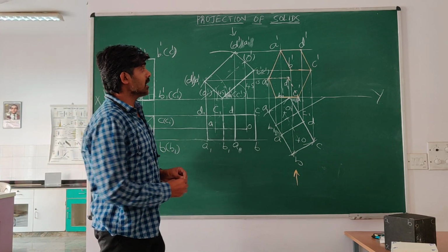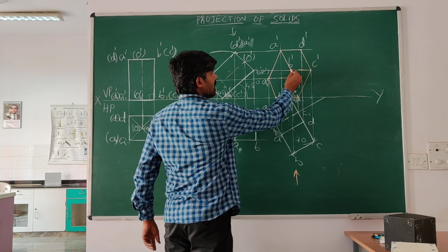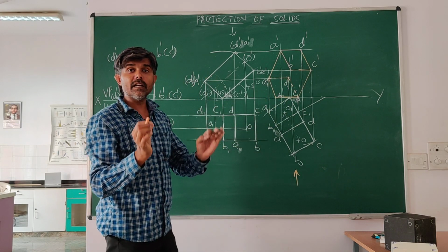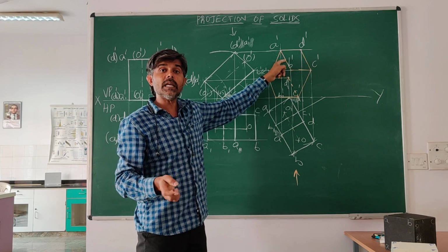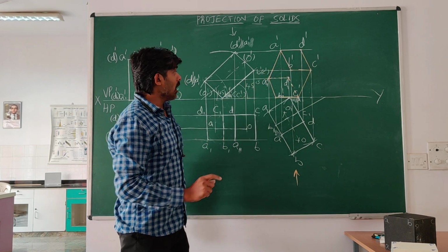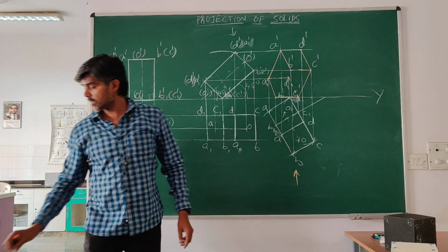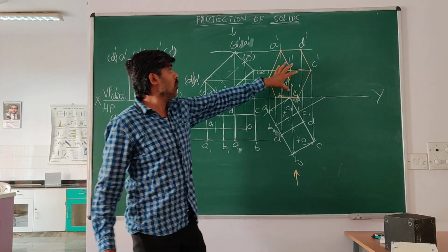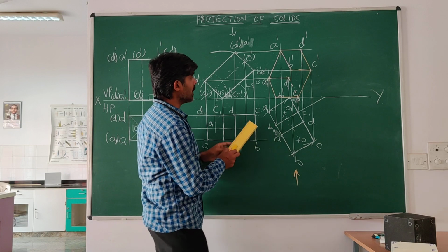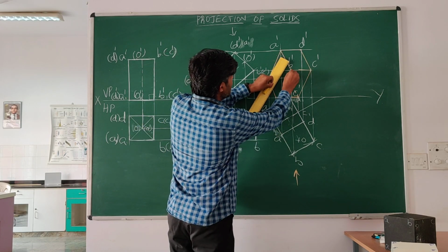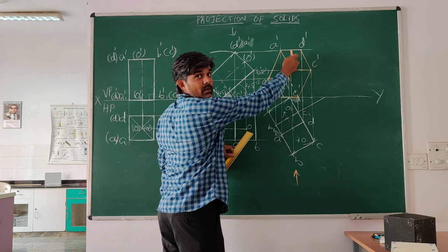If a line is starting from the end or the boundary of a visible face, that line will be a visible line. Some teachers tell it like this: the lines going outside the visible face are visible lines. Because it is starting at the end, it is not coming inside the visible face.